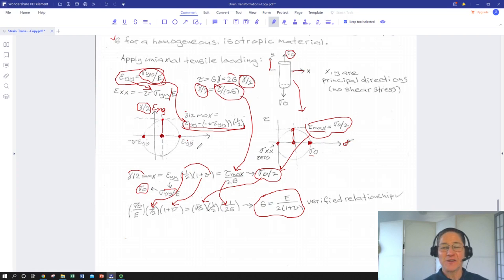So that is it for derivation of strain transformations using geometry, chain rule, definition of strain and displacement relationships. We didn't go through every step rigorously, but we showed how they could be rearranged to give the cosine, sine, 2 theta terms that could be used to plot a Mohr circle. We reinforced how angles in the part, relationship between an x and an x prime, any kind of rotation angle on the part is represented by twice that angle on the Mohr circle.